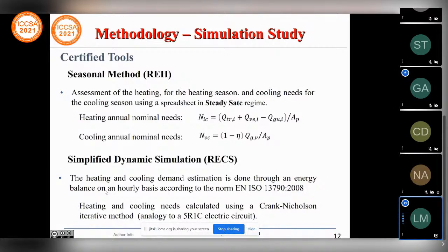This is a different and simplified approach when compared with Energy Plus. Energy Plus uses semi-implicit Crank-Nicolson and finite difference methods, which is much more accurate, or should be more accurate, in terms of the dynamics of the inertia of the envelope walls of the building. And again, the radiation is also treated in a more accurate way.